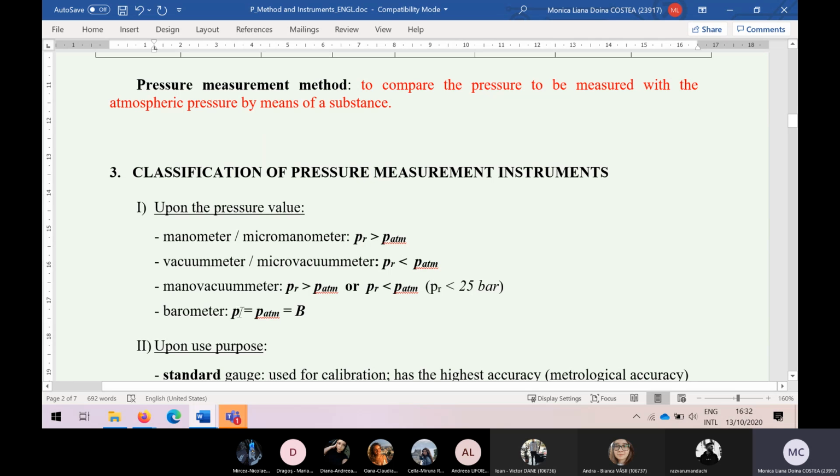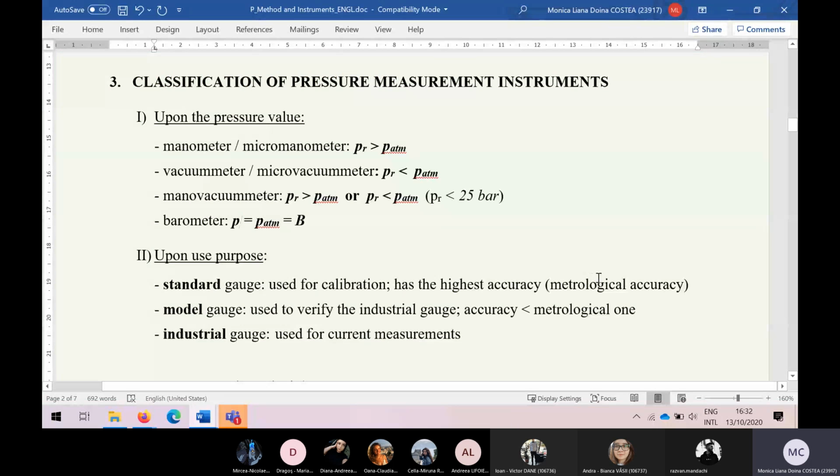It is not a mistake here. P is the notation for absolute pressure, but we are allowed to put the equal sign because, for example, a compressor for the intake air takes the air from the surroundings, which is at atmospheric pressure, and of course this is the absolute pressure at the intake. Otherwise we would say that it's a relative pressure and we would consider twice this atmospheric one, which is not correct.